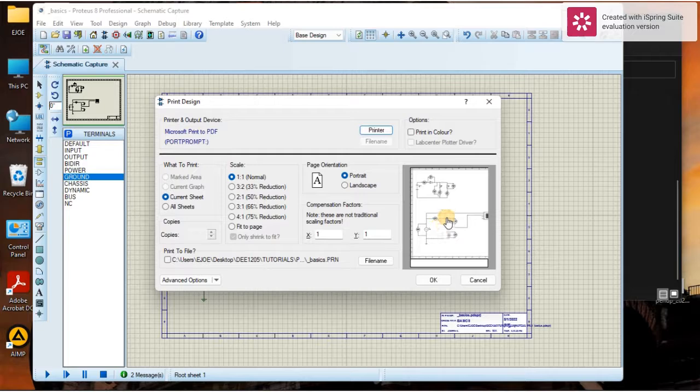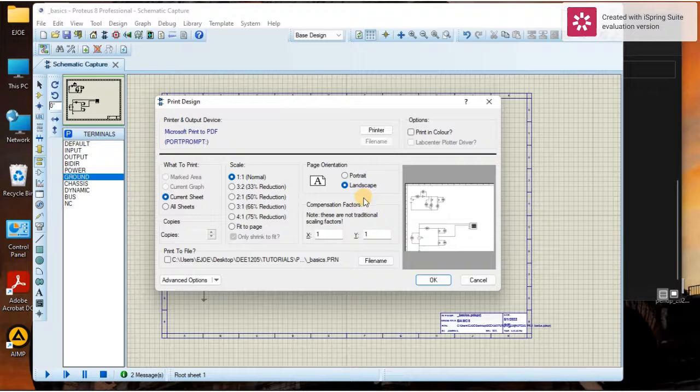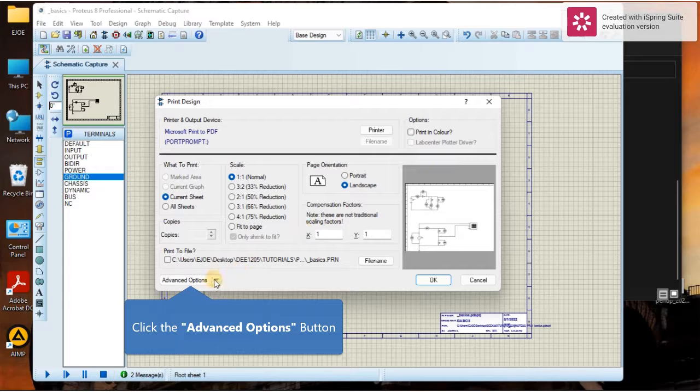Now we can center the plot, and also our page is in portrait and yet the template is landscape, so you can switch this first to landscape, and then see with normal fit, because we are printing on an A4 paper, and the problem is our template is A3, so we either shrink that, or there's actually no option for the A4 printer here.